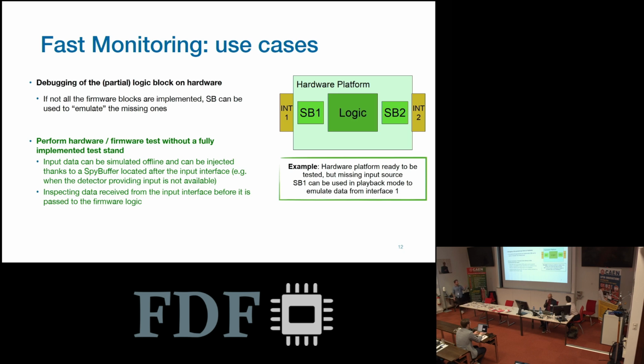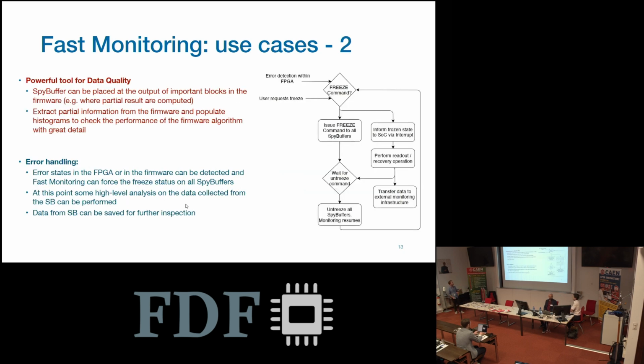But also at the same time, let's say that you have your hardware platform, and this is supposed to be integrated in a more complex environment, where you have some other electronic devices sending you inputs. In that case, if one of these devices is missing, you can use Spybuffers to emulate the interface, or also to inspect the data that is received by an interface without the need of processing it through the whole logic of the rest of your firmware.